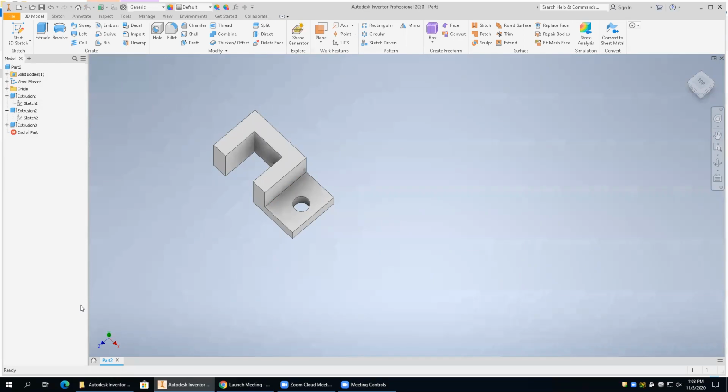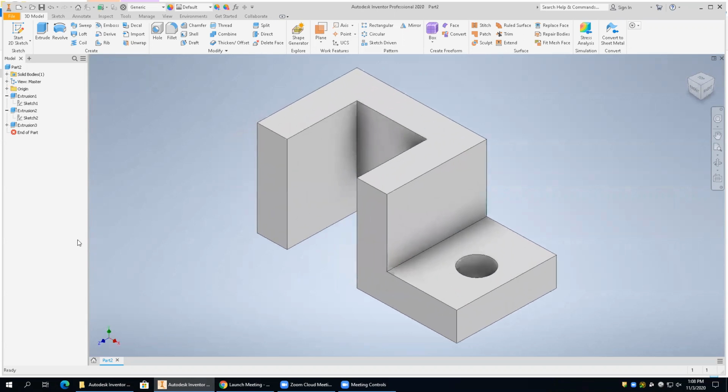A sketch and extruding it, or we can do a hole tool, which does it all in one shot. Okay. All right, so we're going to do one more thing here, and then we're almost done with this piece. Go ahead and do an F6. We're going to notch out a corner here. And this is a little tricky, but it's also kind of cool because it's going to show you how you can use some dimensions. Pretty neat.